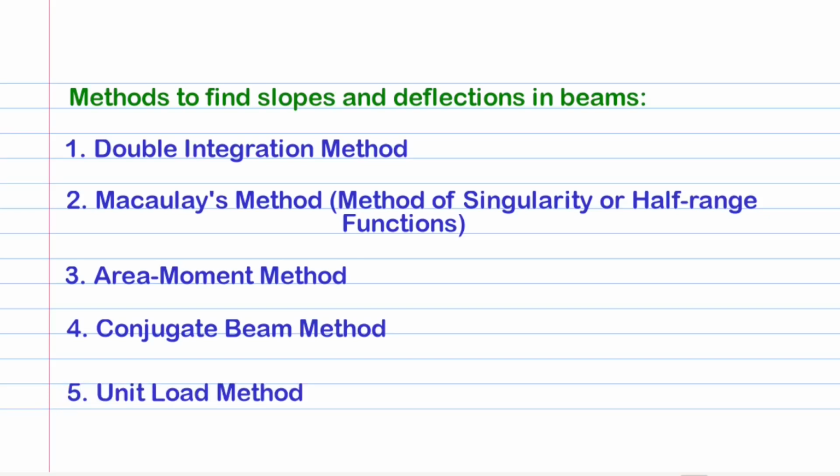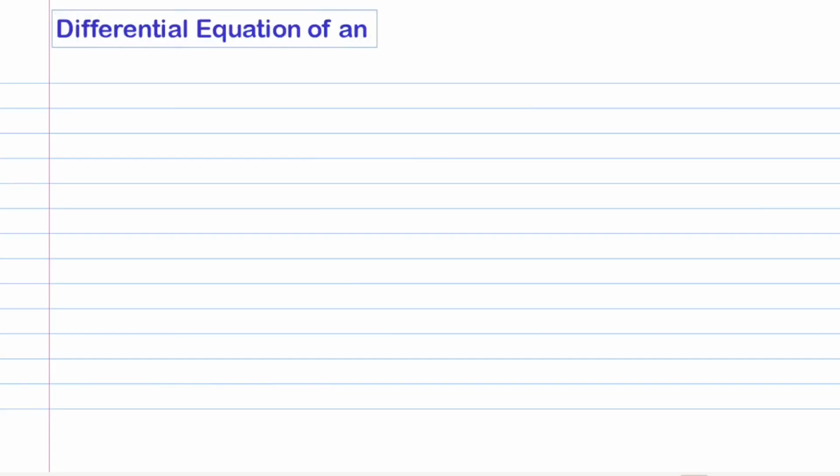We shall specifically emphasize on the double integration method to start with and shall primarily rely on the extension of the double integration method, that is, Macaulay's method, in this course. Other methods mentioned here are outside the scope of present discussion. Before we try to understand the double integration method to calculate a beam's slope and deflection, let's first go through the differential equation of an elastic curve.